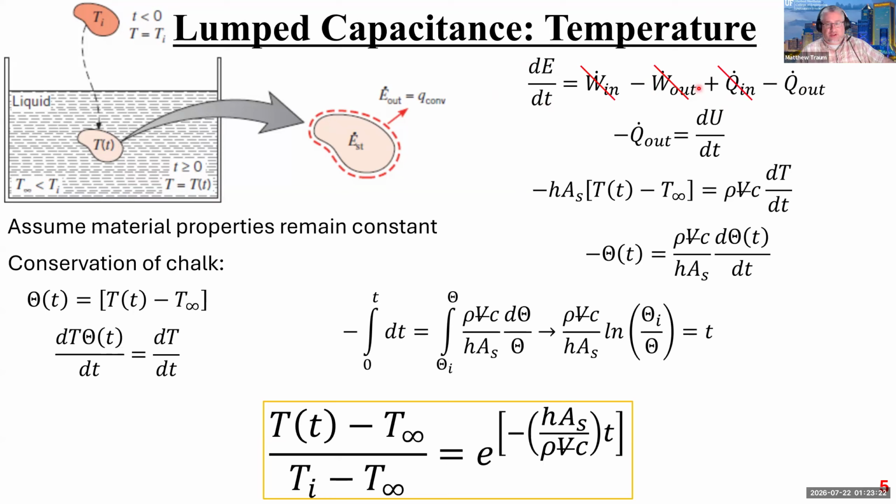As I think I've told you before, whenever you write the first law of thermodynamics, please write it this way. Do not write that delta E equals Q minus W nonsense. That is not correct. You get taught that way because people are lazy and like to write fewer things. But delta E equals Q minus W is only true for cycles, and this is not a cycle.